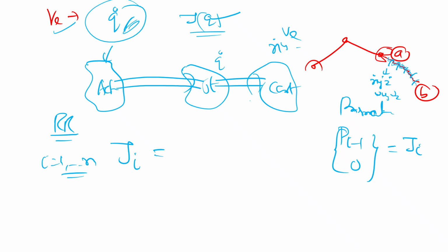The top one is always linear velocity, and this one is angular velocity. For the prismatic joint, you will not have angular velocity, you will have only linear velocity. So the linear velocity formula is the position vector Z(i-1) for Ji. Whereas for the revolute joint, the Jacobian is Z(i-1) cross, because they are perpendicular to each other. That is by cross product.